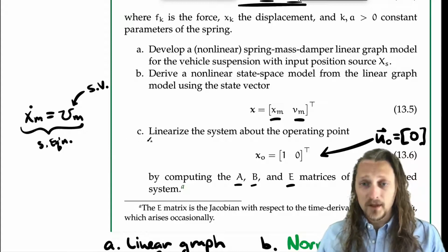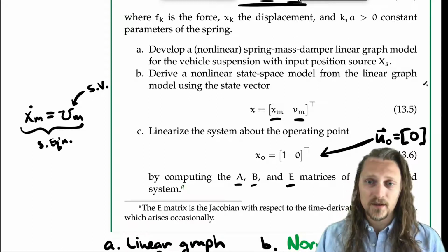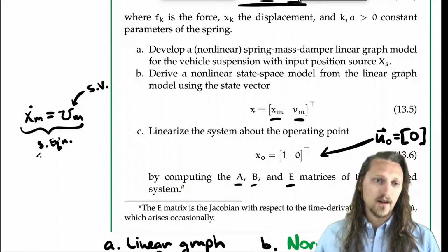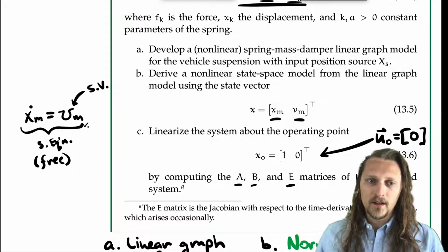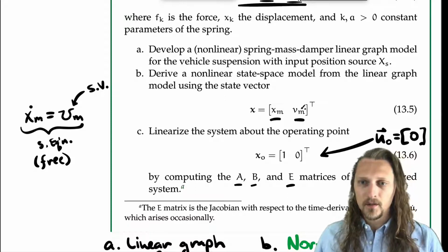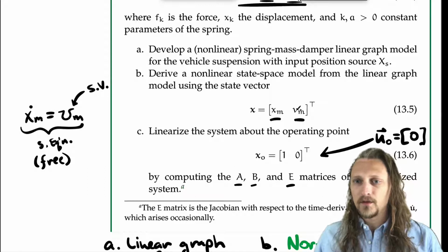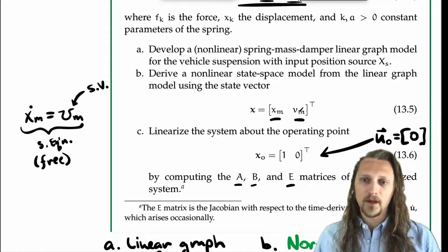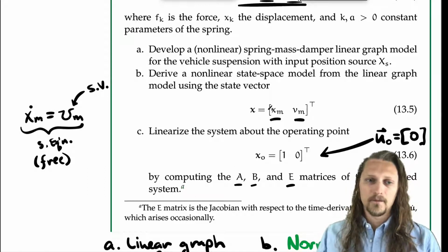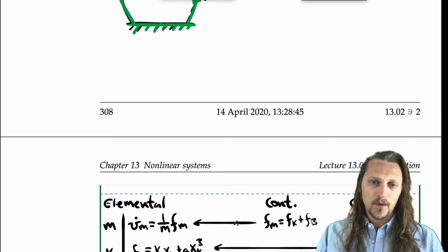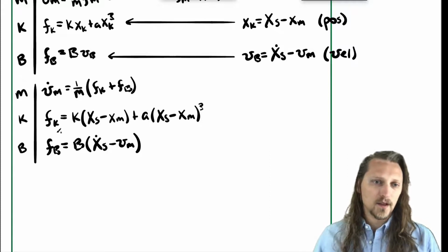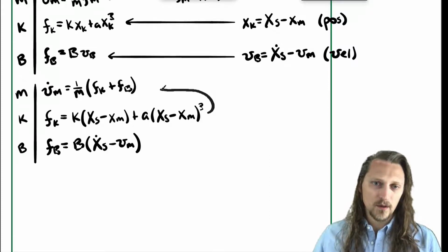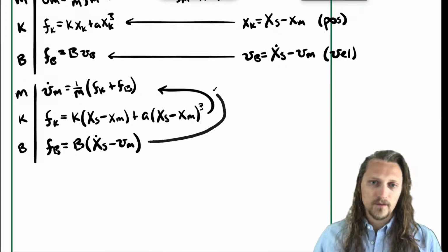So we already have one, and we actually have had one since we wrote this as our state vector. This one sort of comes for free. So really all we're looking for in the rest of the analysis is the state equation for Vm. So we're looking for an equation in Vm dot. And we can actually do that here by substituting these 2 lower equations into the first equation.